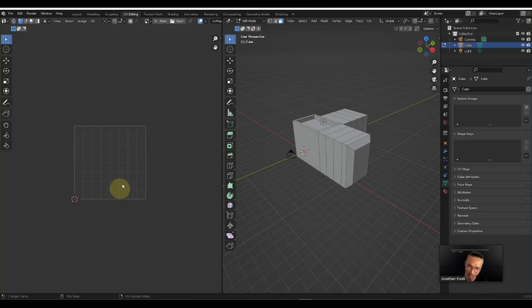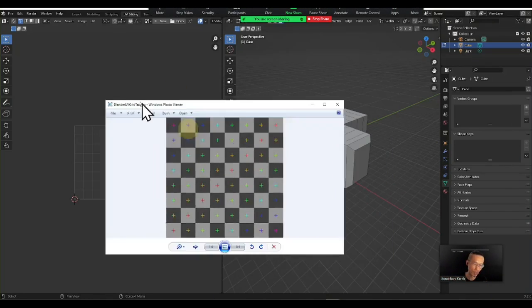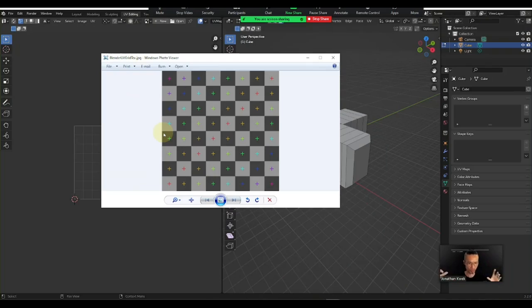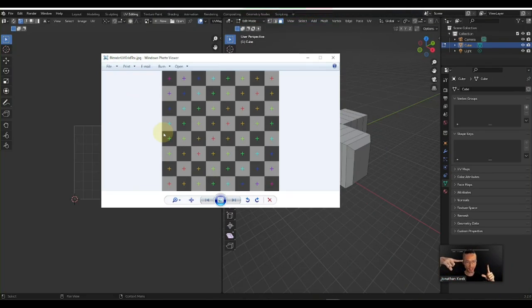Okay? And it starts from the bottom left-hand corner and works its way up to the top. UV coordinates actually only go from 0 to 1, right? So 0, 0 being the bottom left-hand corner over here, and 1, 1 at the top right-hand corner over here. This UV space will map itself onto your texture, irrespective of its shape. Whether it's a rectangular shape that looks like this, or a rectangular shape that looks like this, it's 0 to 1. 0 on one corner and 1, 1 on the other corner. So it's the same throughout, no matter the shape of your texture.